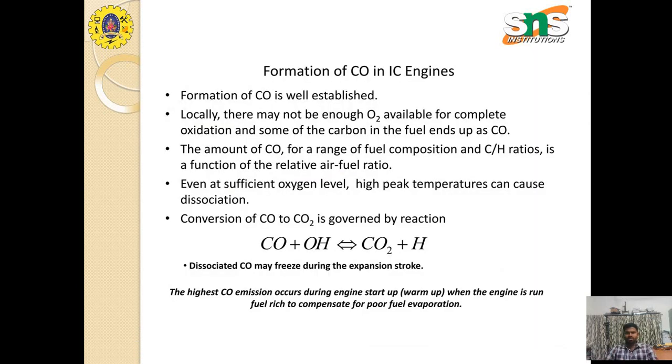Now, the formation of carbon monoxide in the IC engine. There may not be enough oxygen available for complete oxidation, and some of the carbon in the fuel ends up as carbon monoxide. The amount of carbon monoxide, for a range of fuel compositions, that is the carbon to hydrogen ratio, is a function of the relative air-fuel ratio.